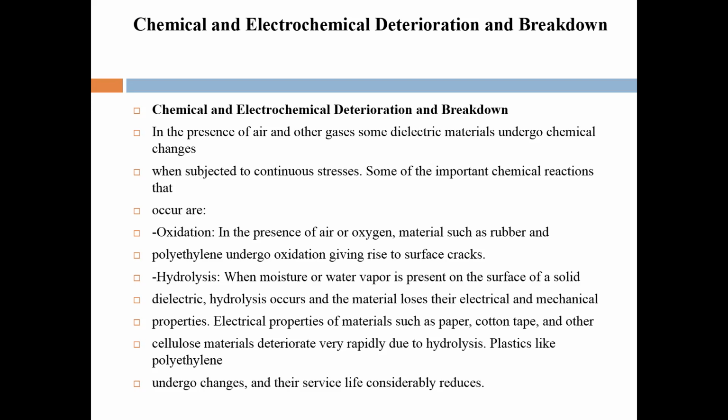Now, second one, hydrolysis. When moisture or water vapor is present on the surface of a solid dielectric, what happens? Hydrolysis occurs, and the material loses its electrical and mechanical properties. When the material loses its electrical and mechanical properties, surely you can say that it can easily be subjected to breakdown, because these properties are going to change, vary, or be lost.